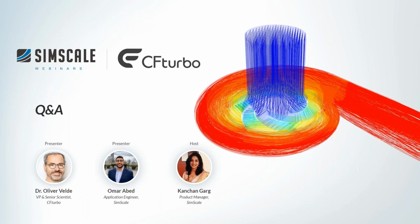So there's a lot of ways for you to get literature based on a cast iron element versus a smooth wall of how to define that roughness constant within your stationary walls. There's some documentation available on the SimScale platform, as well as literature all over that can help you define that parameter. But it's really just a single input to define a wall roughness, which determines what's going to be happening near the walls in terms of pressure loss and turbulence.